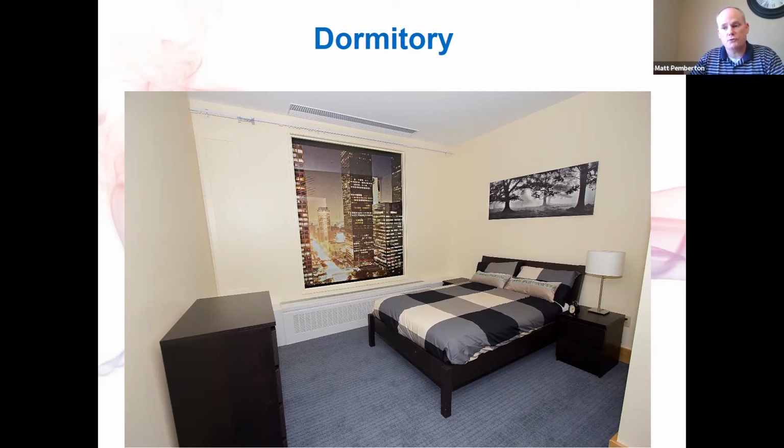And that's also true when it comes into the healthcare arena with the hospital patient rooms. Those have air change rate requirements also. And that changes to say it's not a filtered air change requirement as long as you're inducing air from the same space and distributing it back into the same space, meaning we couldn't return air from 3 different rooms and then supply it back to 3 different rooms. The chilled beam is in a zone. It's only drawing air from that zone and returning air to that zone. So it's considered an air change and not a required filtration air change. So I agree with you. The code would have to be reviewed for each individual style of specific lab you were doing to see if it allowed for air changes without filtration.